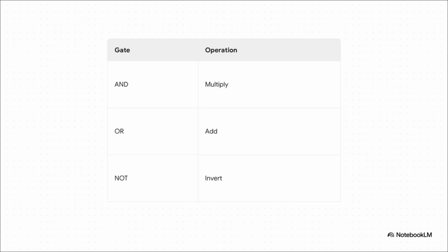Deep inside that ALU we just mentioned, the actual physical computing is performed by logic gates. These are literally physical transistors in action on a microscopic scale. The foundational gates are AND, OR, and NOT, alongside a couple of others you'll encounter like XOR and XNOR. And those truth tables you see? They aren't just math assignments. They define the absolute unbreakable logical rules for exactly what output voltage you will get from these gates based on the inputs you feed them. If you can understand these simple truth tables, you basically understand the foundational logic of all computer hardware on the planet.